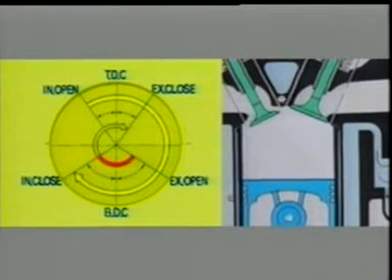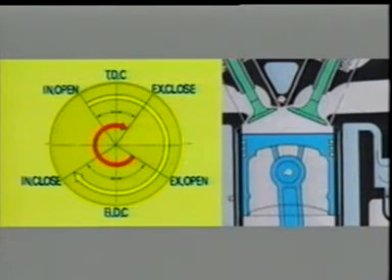The exhaust valve begins to open before BDC of the combustion stroke. It opens early in order to be sure that all the unneeded exhaust gases are expelled from the cylinder. The exhaust valve shuts after passing TDC of the exhaust stroke. This is done in order to utilize the inertia of the exhaust gases to clear them out of the cylinder.